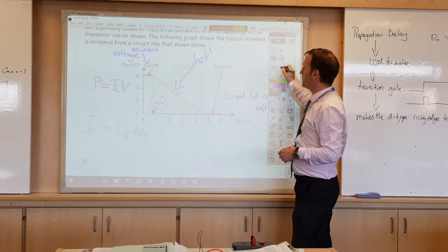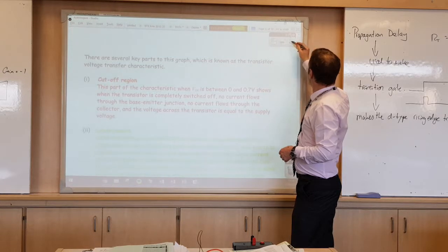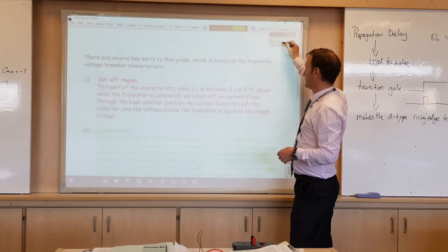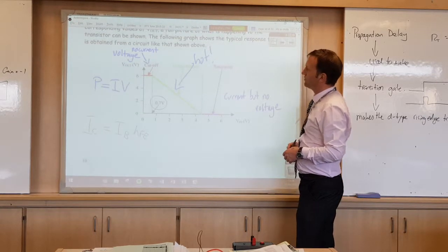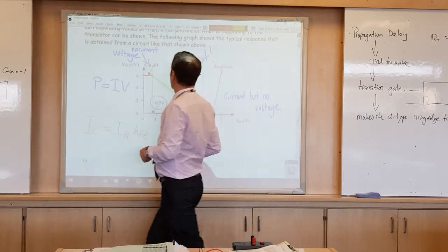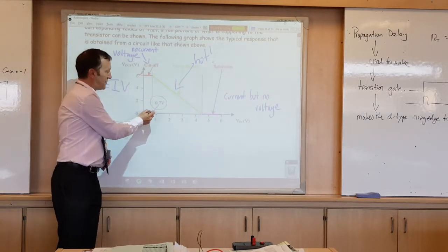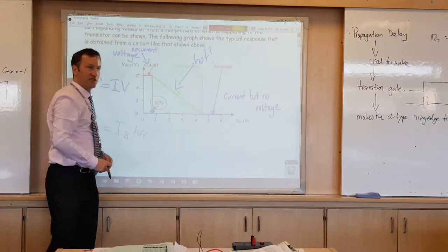So how do we work this out? Well, we have to be able to sketch this graph. We need to establish the voltage level here, easy enough, because that's the power supply voltage. This one never changes, so we know this point here at 0.7 never changes.